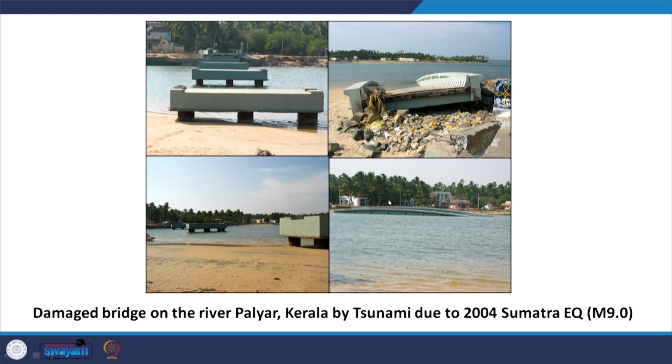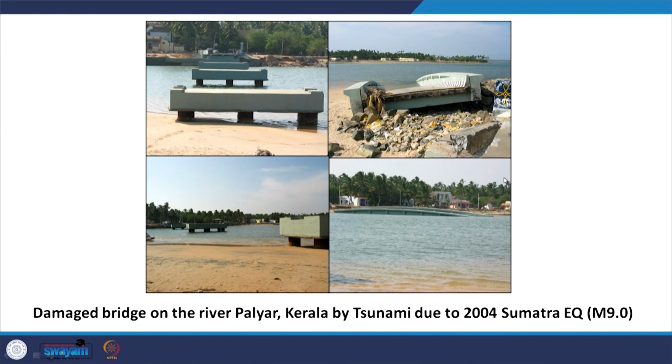We examined the reason for this collapse of the deck, and we found that there was separation of the span from the bearings here. So, it could be said that the bearing failures of this bridge led to the collapse of the span.